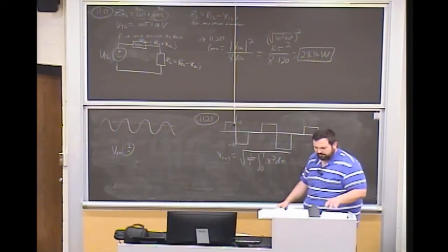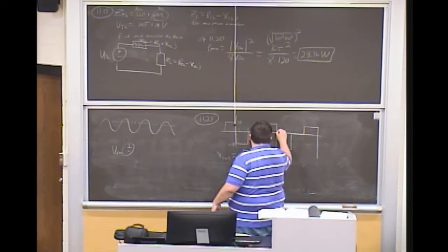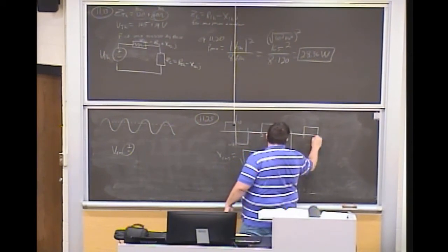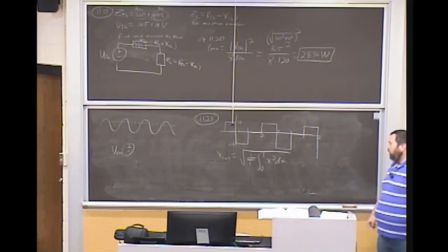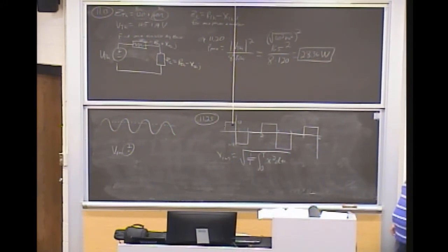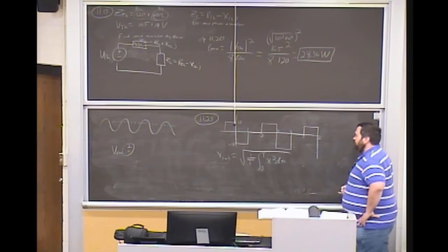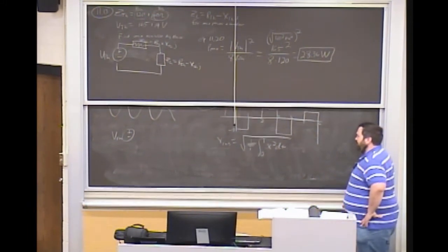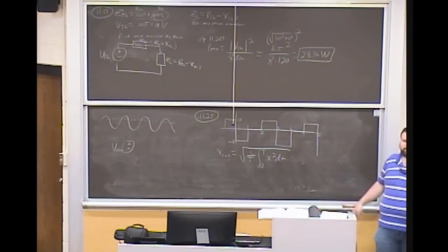Oh, let me also give you time units. So each of these steps happens in basically 1 second intervals. Okay? What is the period of this signal? 3 seconds. 3 seconds. And so the full period of this is going to be over 3. So I'm going to plug that in for my t. And effectively, I don't have a continuous function in here, do I? So what I'm going to do is integrate it piecewise.